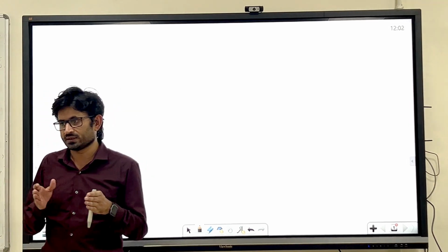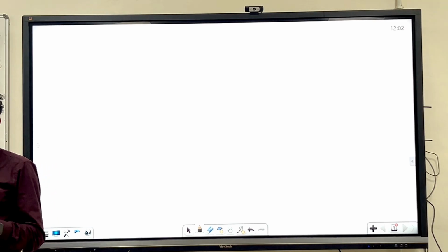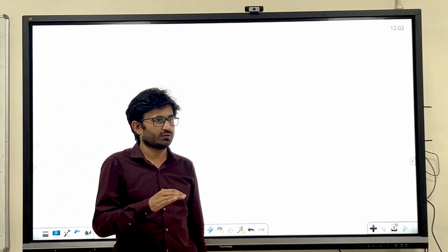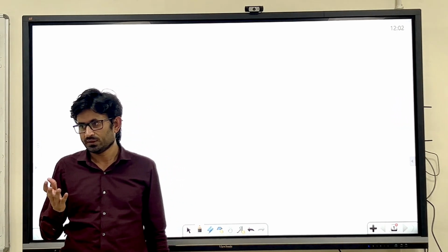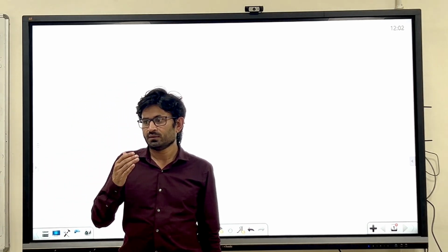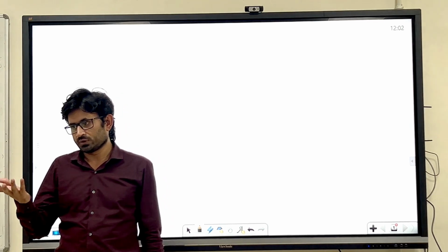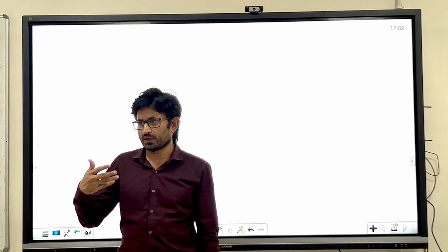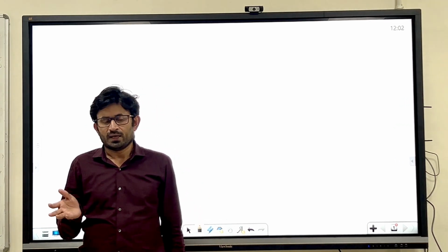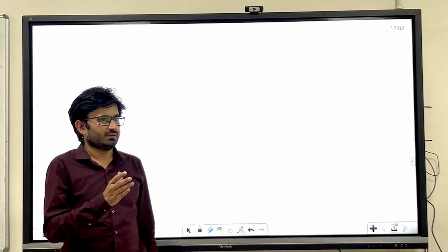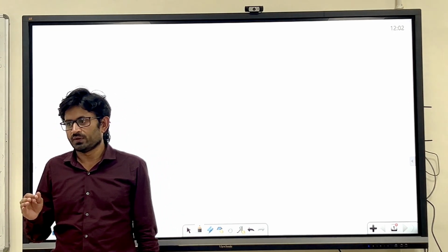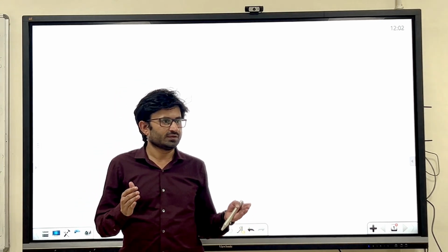Okay. What is static stability? What is dynamic stability? Static stability means the inherent tendency to return to its equilibrium position when it is disturbed. That is static stability. When it attains a new equilibrium point, in that case it's a neutral state. And when it diverges from its equilibrium point, then it's called an unstable system. Dynamic stability means the system will take some time to reach the equilibrium position. When time comes into the picture, then we say dynamic stability.